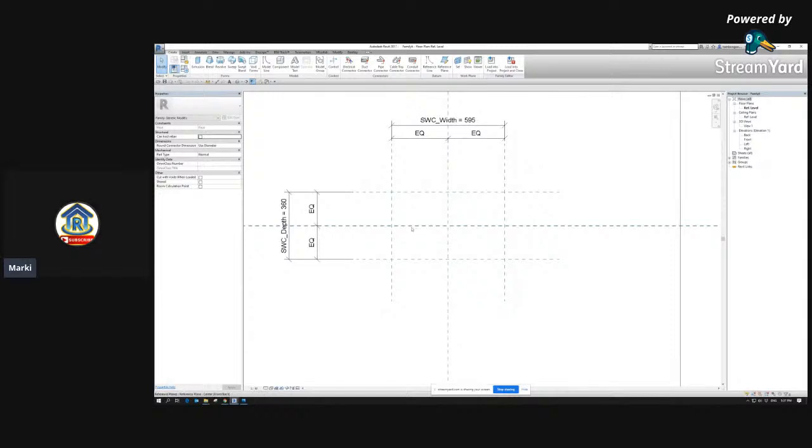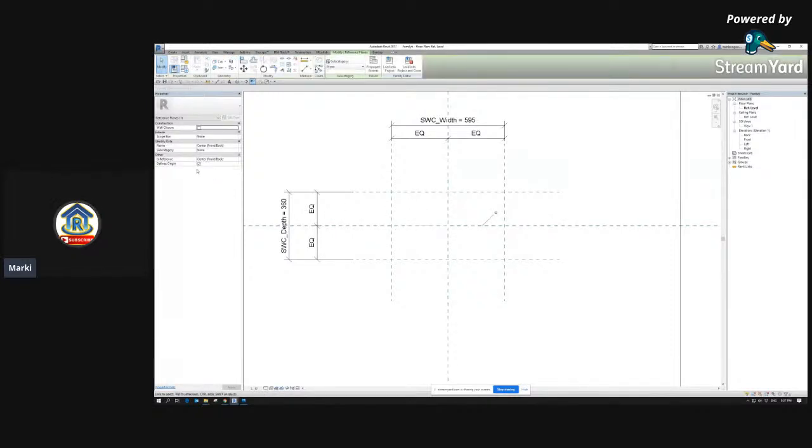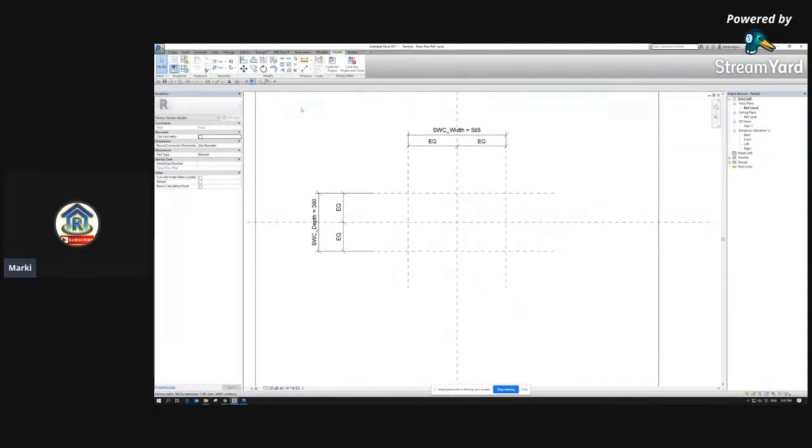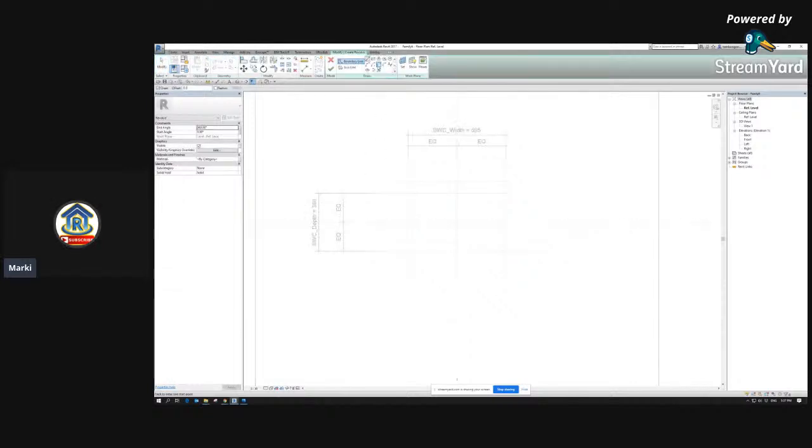So from here, the origin is the center front back and the center left right. So what we can do is simply shift the defining origin to this left hand side, define origin, and then pin it, pin to pin, and then unpin the center left right. And then we can just simply fix this as an origin because it's a revolve. So what we can do is command our revolve, create revolve tool. There you go, revolve.